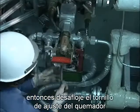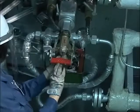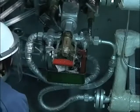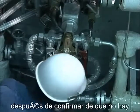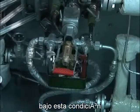Then loosen the burner attaching bolt. Carefully pull out the burner after confirming that there is no blowing off of fuel and steam under this condition.